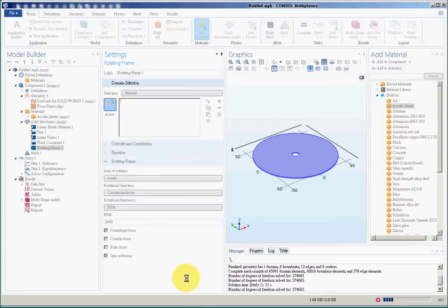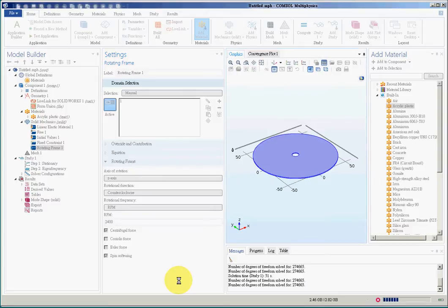At higher rotating speed, a higher prestress builds up in the compact disc. So the internal stress of the CD increases. So the CD becomes more rigid or more stiff. Therefore, the stiffness or the rigidity of the structure increases, and also increases the natural frequency.